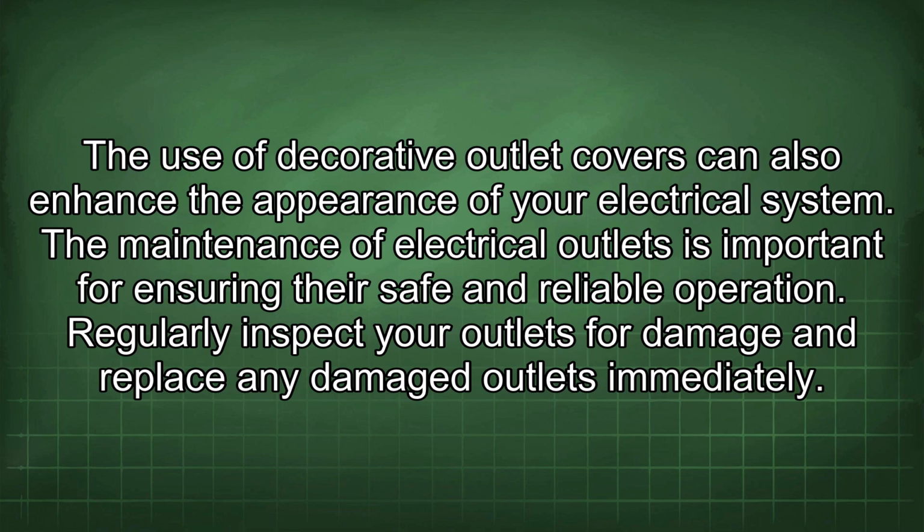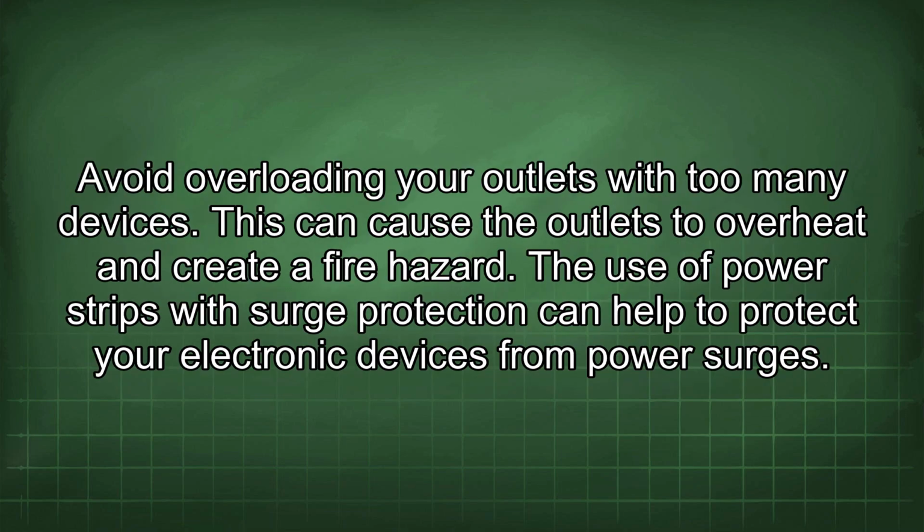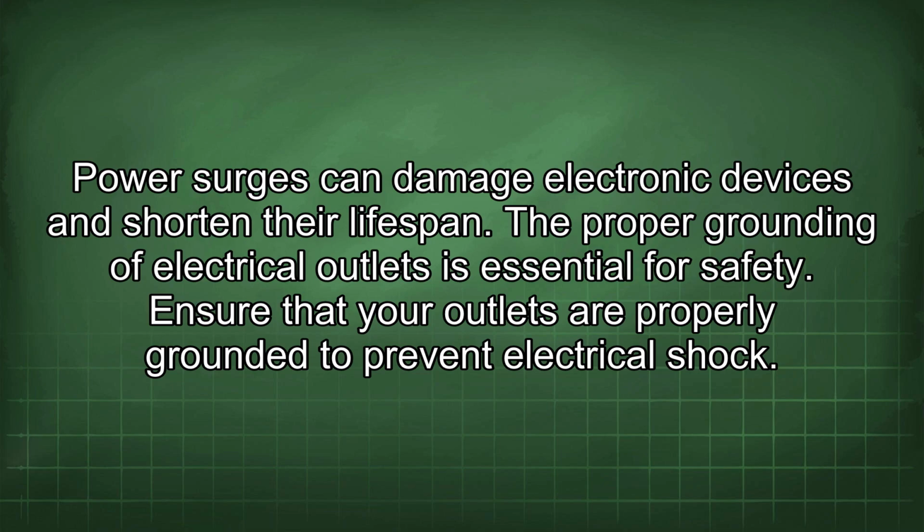The maintenance of electrical outlets is important for ensuring their safe and reliable operation. Regularly inspect your outlets for damage and replace any damaged outlets immediately. Avoid overloading your outlets with too many devices. This can cause the outlets to overheat and create a fire hazard. The use of power strips with surge protection can help to protect your electronic devices from power surges. Power surges can damage electronic devices and shorten their lifespan.